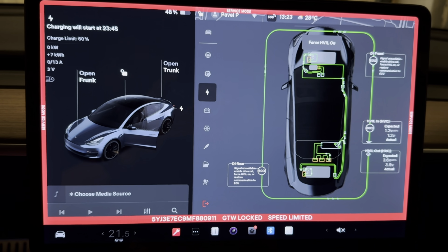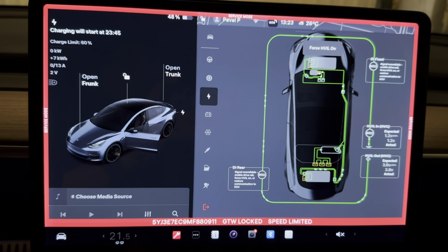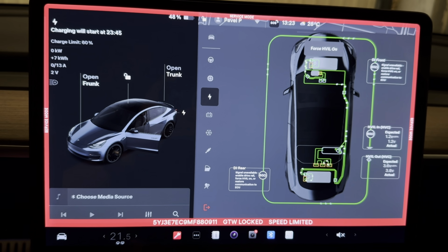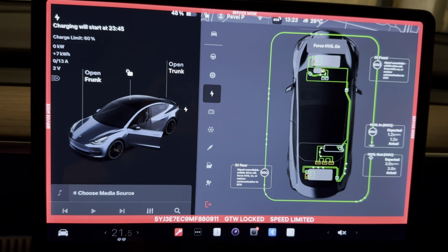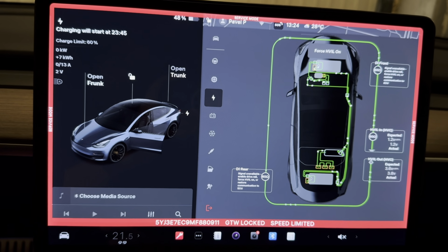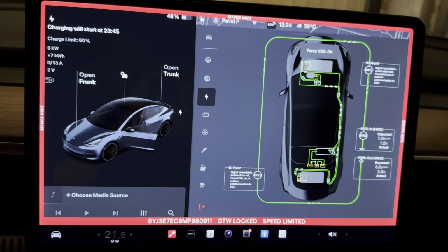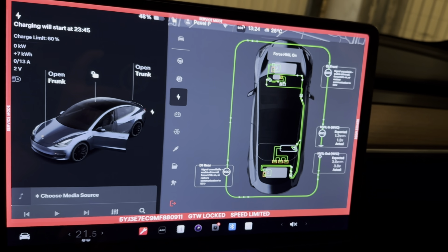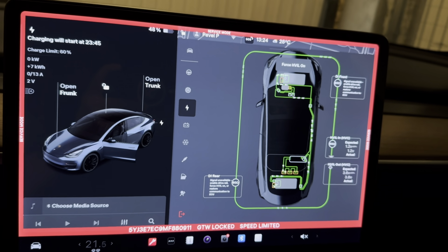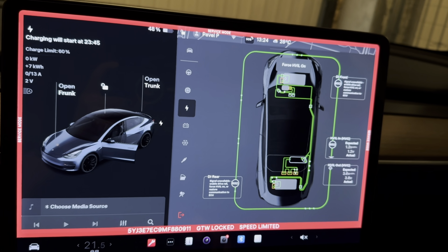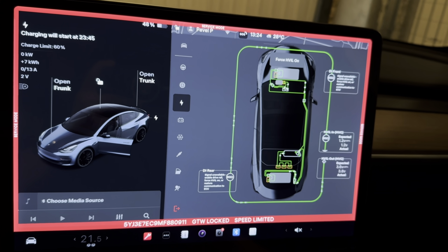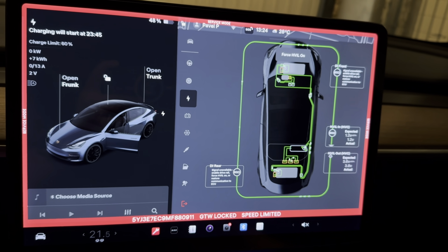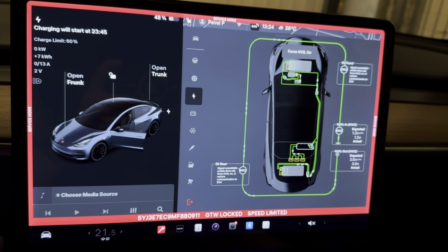It should be a so-called floating type of circuit. That means that the circuit is completely separated from the vehicle. This is done so that you don't accidentally fry yourself if, let's say, the wire is grounded to the chassis of the car. So the minus of the battery is a separate one. It's not using the chassis of the car like the 12 volt.